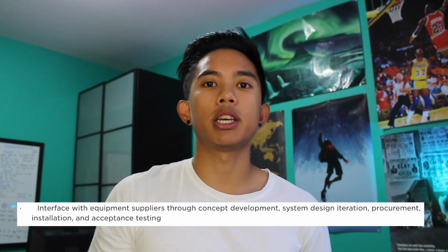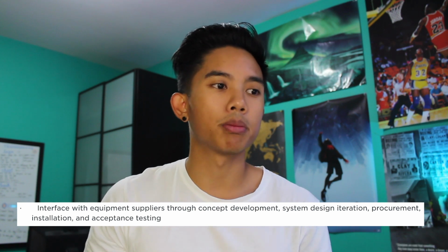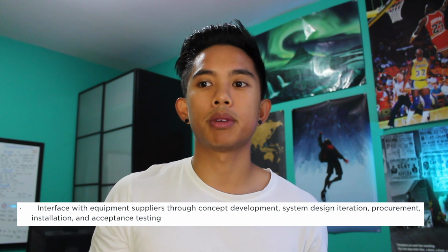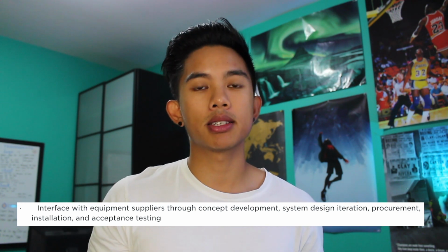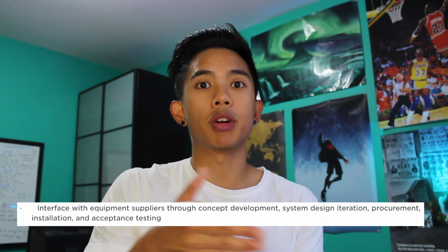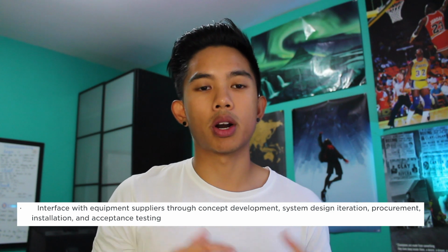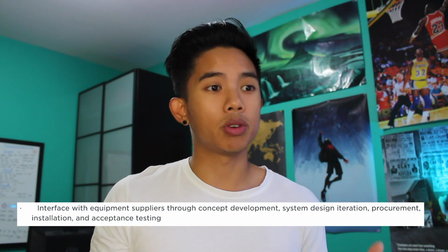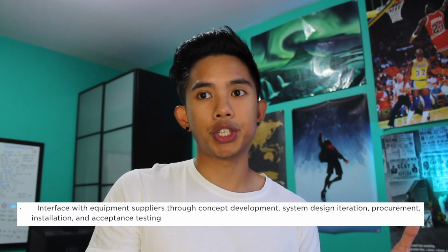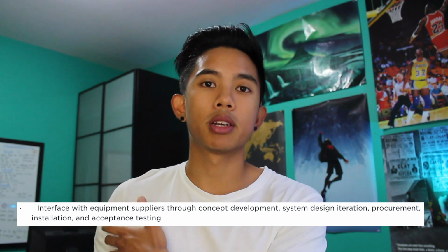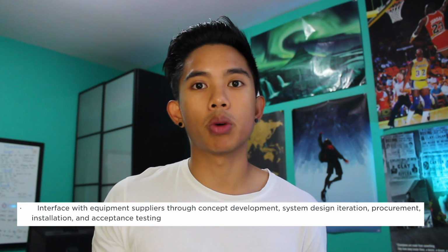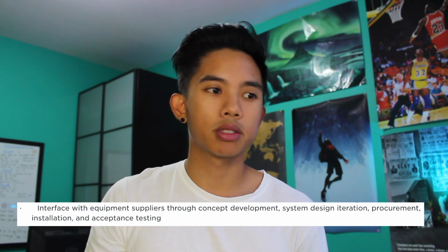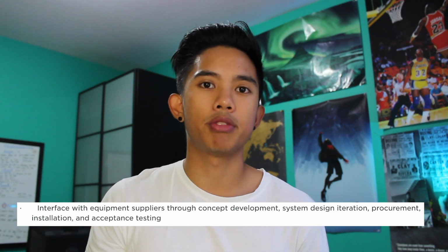And as you gather this information from vendors and equipment suppliers, you'll iterate on your system design. Oftentimes you'll start with something that thermodynamically makes sense. Maybe the configuration you have within your heat exchangers and separators was no good, and maybe that was a costly iteration. But if you flipped the configuration of the things within your plant, maybe that lowers the entire cost of things or improves the efficiency of your plant.